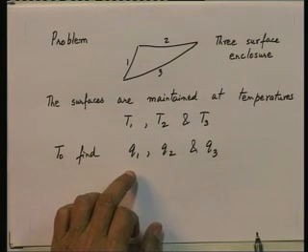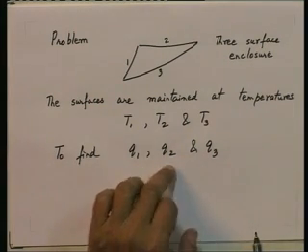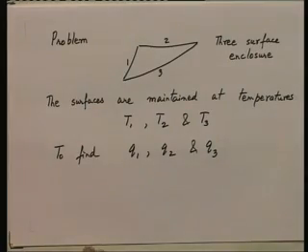It is just the same earlier 3 expressions that we had, but now in this case you know the values of EB1, EB2, EB3. So, you can directly from the 3 equations which I put down earlier get the values of Q1, Q2 and Q3. So, the point I want to make is, for any one of the surfaces, you need to specify either the rate at which heat is supplied at the surface or the temperature of the surface, either the Q for the surface or the T for the surface. And you can find, if one is specified, the other can be found out, right. So, keep that always in mind. In any 3 surface enclosure, if I specify either Q or T for it, the other quantity which is not specified can be determined. That is basically what we can do with the help of the 3 equations for the 3 surfaces.